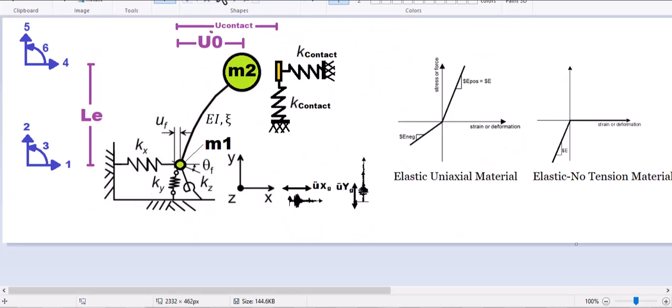In the other analysis, we are going to run the seismic response spectrum analysis. So we are going to change the total mass of the structures. The total mass of the structures equals to this value and this value. So for example, M1 in my model equals 5% of the total mass, and then the mass at the top of the column, which is called M2, equals 95% of the total mass.